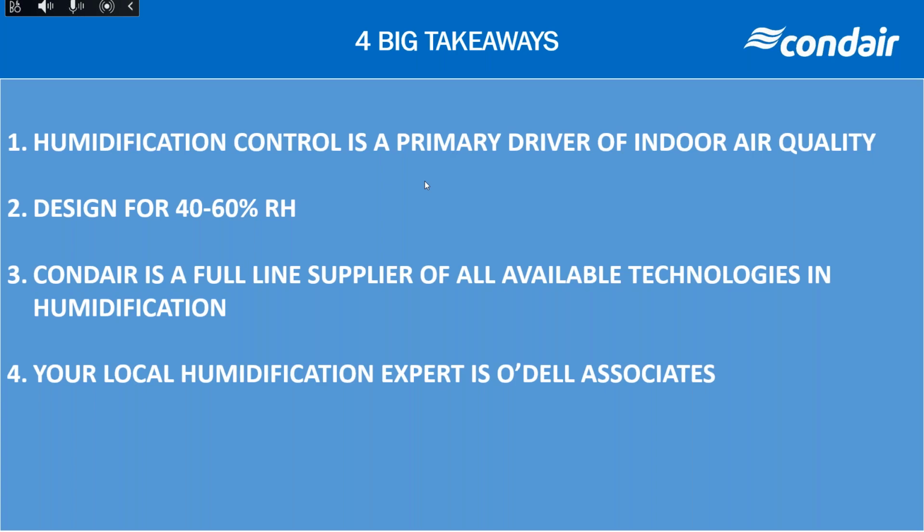I would say they're no more susceptible as long as the water conditioning is maintained with RO, and no standing water is left to sit in an air handler for any length of time, or sit inside piping. All of the Condair solutions do have hygiene flushes and hygiene requirements to make sure that those things don't happen.